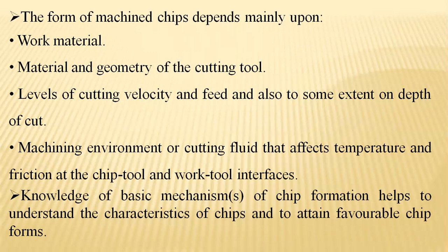For ductile materials, high depth or high feed rates can be accepted. But for non-ductile or brittle materials, high feed rates cannot be used, and the process has to be progressed under detailed examination.